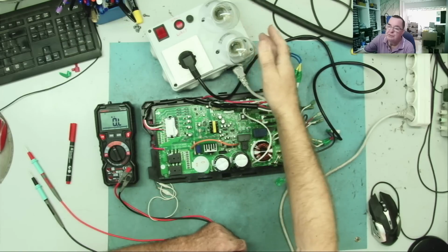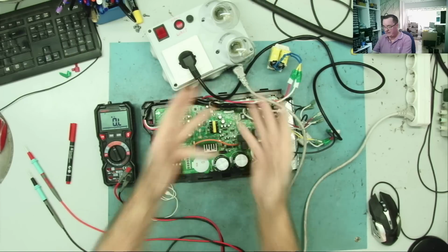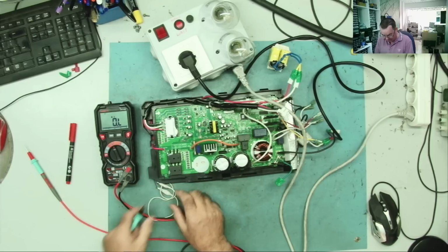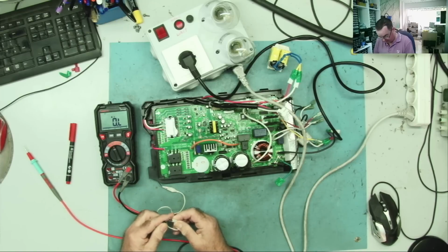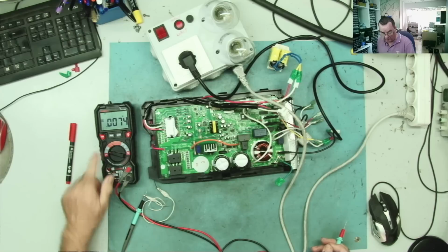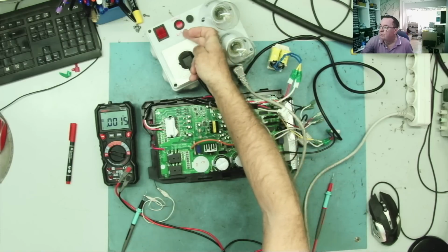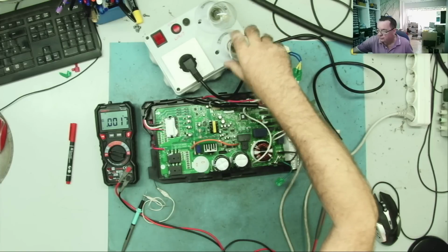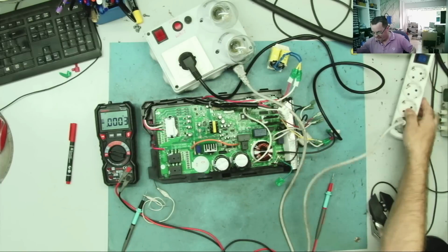We have 2 72 watt bulbs here, so we have a total of 144 watts. That means that they will light up dimmer if this is drawing the same current, so there'll be more voltage getting into this. And then we can check the minus 15 volts again and see if it comes up correctly this time, okay? So we go to volts on here. This is set to limit the bulbs. You either use both or you just unscrew one. There isn't a switch to actually switch the other bulb in, but that's fair enough as it is.